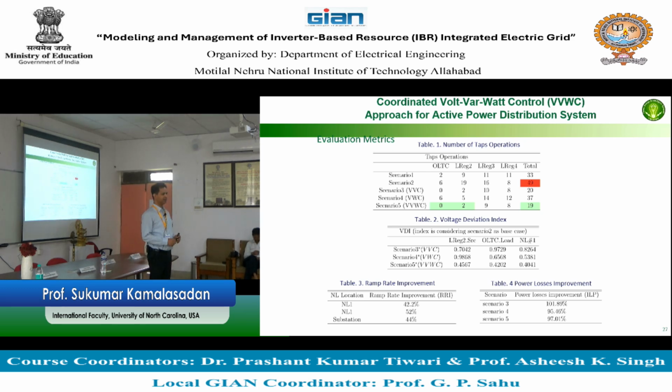So, for a synchronous generator, the ramp rate for pushing the power from the synchronous generator to the output is around 2 seconds, 3 seconds, including all the loops connected with that. So that's basically including the ramp rate of the synchronous generator. For photovoltaics and other devices, the ramp rate is even faster.